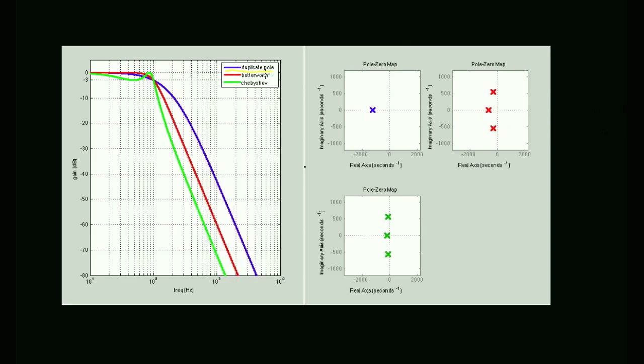If you look at it, there's actually no reason to take the duplicate pole filter, because it has worse performance in the stop band, and it also has worse performance in the pass band. You see how the red filter is flatter for more frequencies? It's giving you better fidelity over more frequencies than the blue one. So nobody ever just stacks like that. This is what you would get if you took an RC filter and did three in a row, all of them having the same cutoff frequency. It would be basically the crappiest low-pass filter you could build. That's the technical term for what would happen.